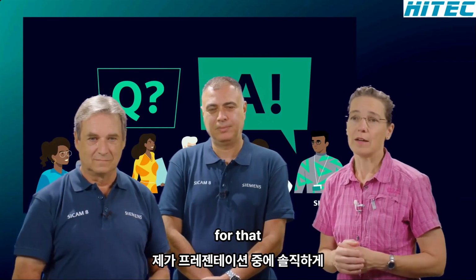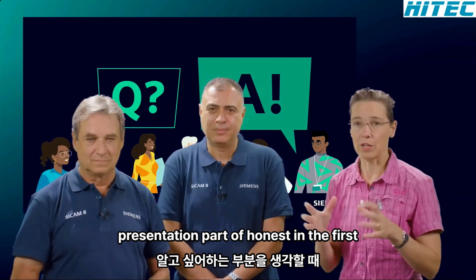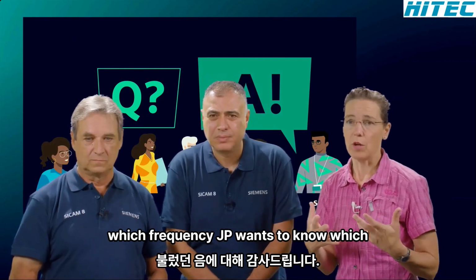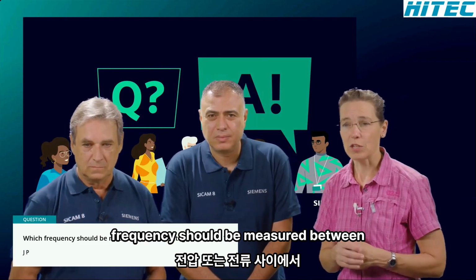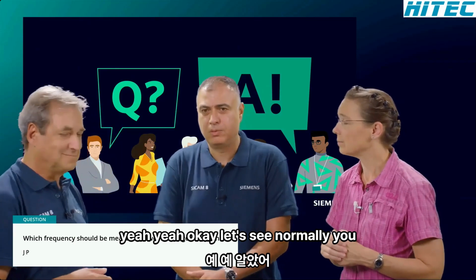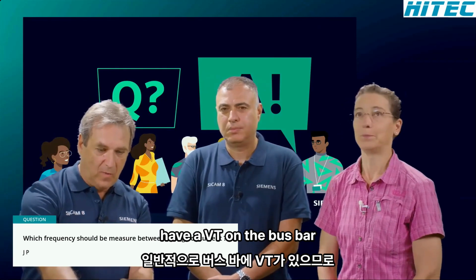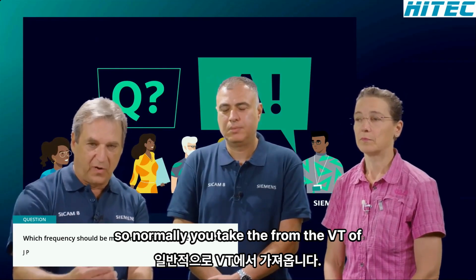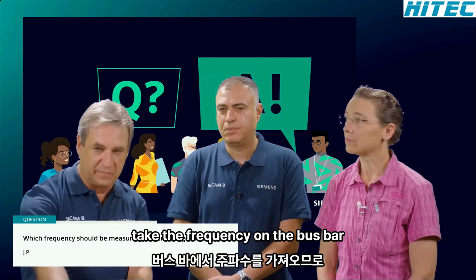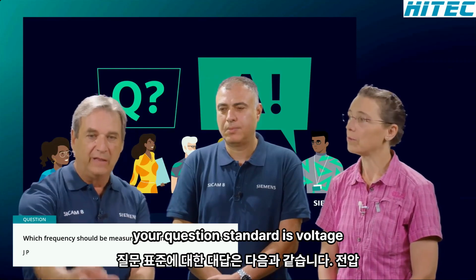Thank you for that. That was somewhere, I think, during the presentation part of Arnes. JP wants to know, which frequency should be measured, voltage or current? Yeah. Okay, let's see. Normally you have a VT on the bus bar. So normally you take the frequency from the VT, of course, you only have the voltage. So the standard answer to your question is voltage.